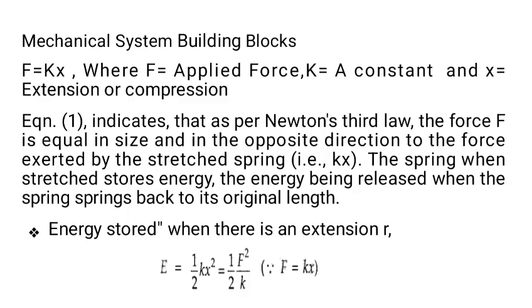As per Newton's third law, the force F is equal in size and opposite in direction to the force exerted by the stretched spring. That is where we call it F is equal to Kx. The spring when stretched stores energy, the energy being released when the spring springs back to its original position. The energy stored when there is an extension x is E is equal to half Kx square, which is equal to half F square by K. Therefore, F is equal to Kx.